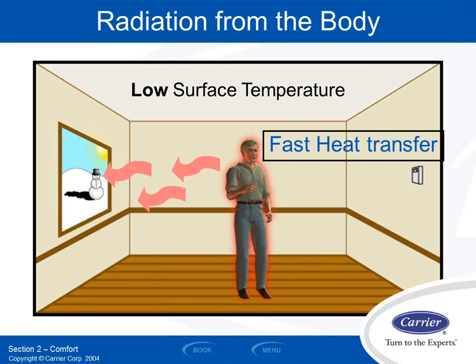The same thing happens when you come into your office building in the morning, in the winter time or even the spring and fall time, and you sit down at your desk, and even though the thermostat in your office says it's, whatever you asked for, 70 degrees heated, and it's 70 degrees, perfect temperature, you got everything you asked for, you sit down at your desk, and you're like, ooh, this desk is chilly, right? The surface temperature of the desk is not 72 yet. We just turned the heat on half an hour ago. We heated up the air to 72. It takes a long time for that air to now turn around and heat up the objects. So your desk is still 60, 65 degrees, so it feels cool when you set your arms down on it.